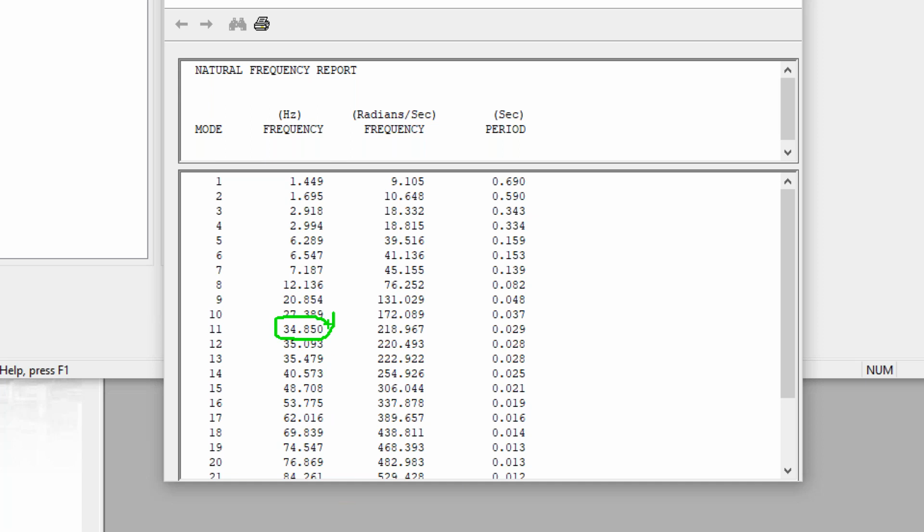So these are the frequencies you have to decouple from the excitation you have. In this case, you would change the spacing of the supports or the rigidity of the supports to decouple this mechanical natural frequency from the ones you're measuring in the field.